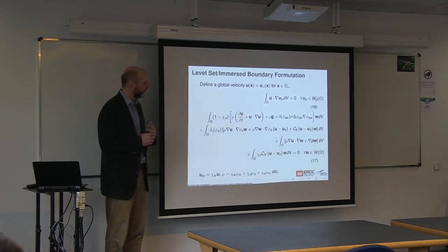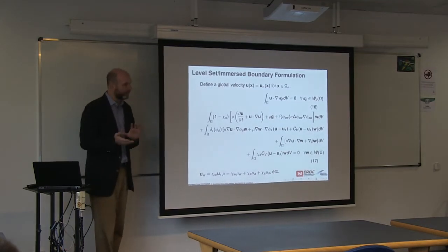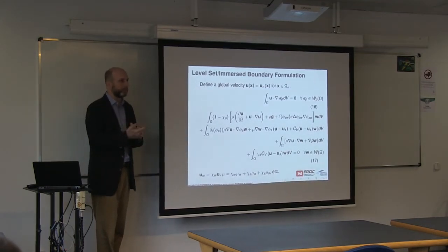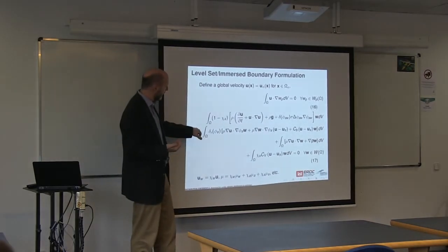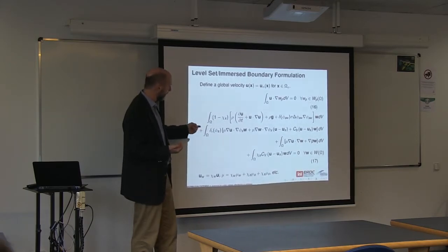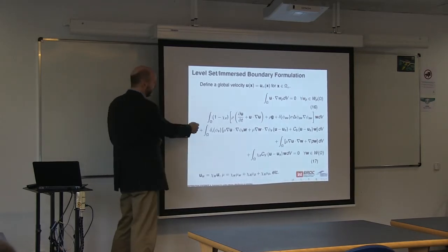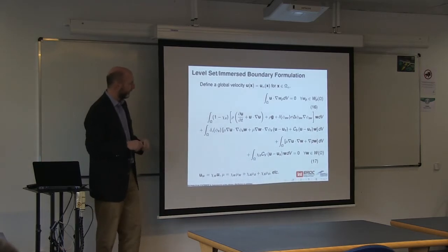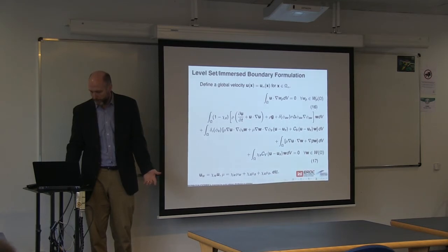So there's a method by Glowinski that uses a Lagrange multiplier approach, and it ends up using a penalty like this. And so I know this is one of those maybe dirty tricks that you find a lot of people are actually doing in order to represent moving solids. It's just putting a penalty in the solid phase. The difference here is that we do have formal consistency through this Nitsche type enforcement of the boundary condition, and that also gives us a precise way to evaluate our lift and our drag by calculating the boundary integrals that are appropriate to get the lift and the drag on the immersed boundary. So that's what we put a lot of our time into.